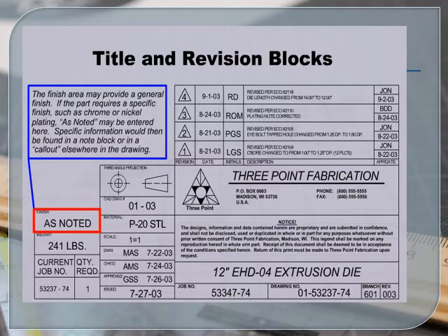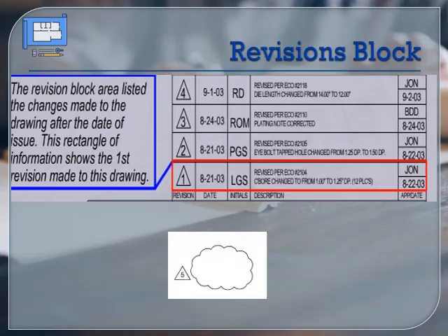In lesson 4, we talked about title blocks, revision blocks, and some other information blocks on your drawings, such as zoning and general and specific notes. So our title block was in the bottom right-hand corner of our drawing usually, and it identified what our drawing was and its number. The revision block called out changes.